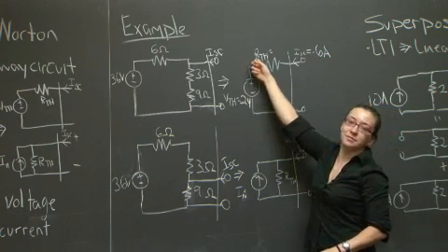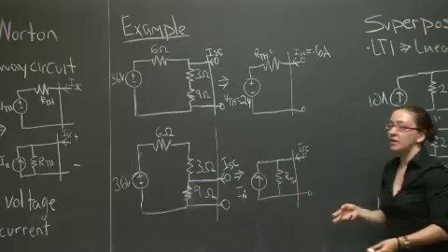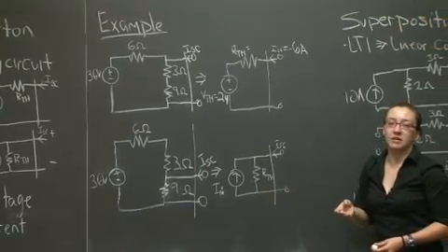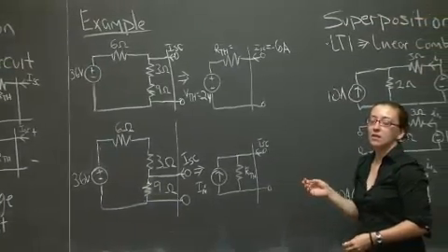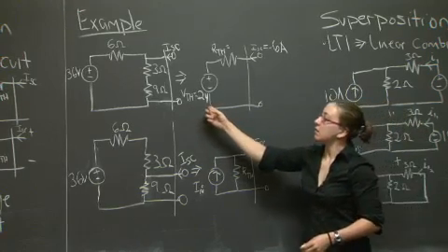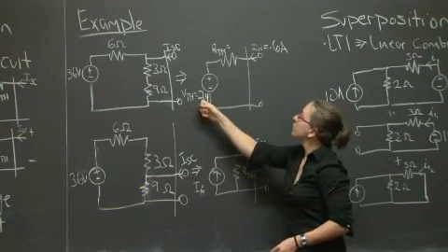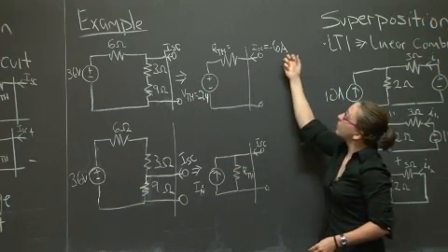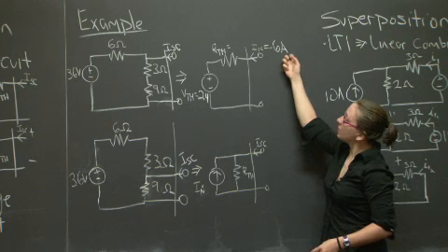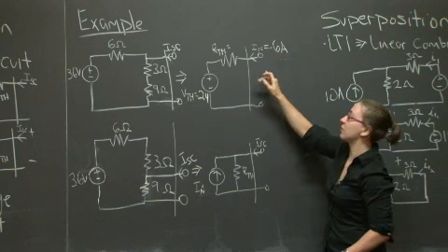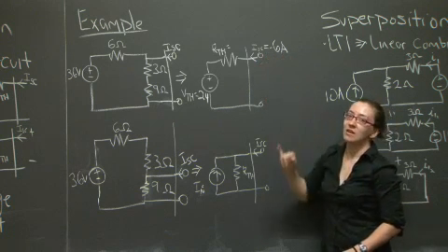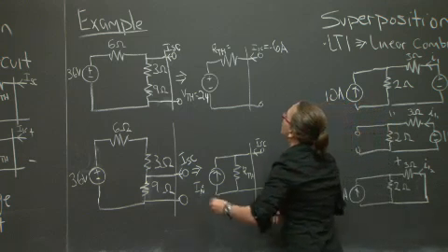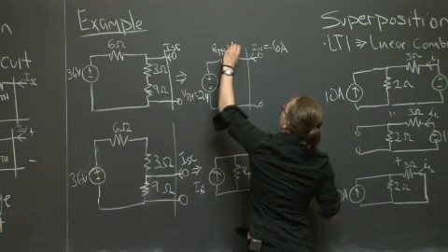That just leaves RTH. Once again, we're going to rely on Ohm's law. If we divide our voltage by our current, you can't have a negative resistance. We're actually going to divide by the negative of this. We'll get out 4 ohms.